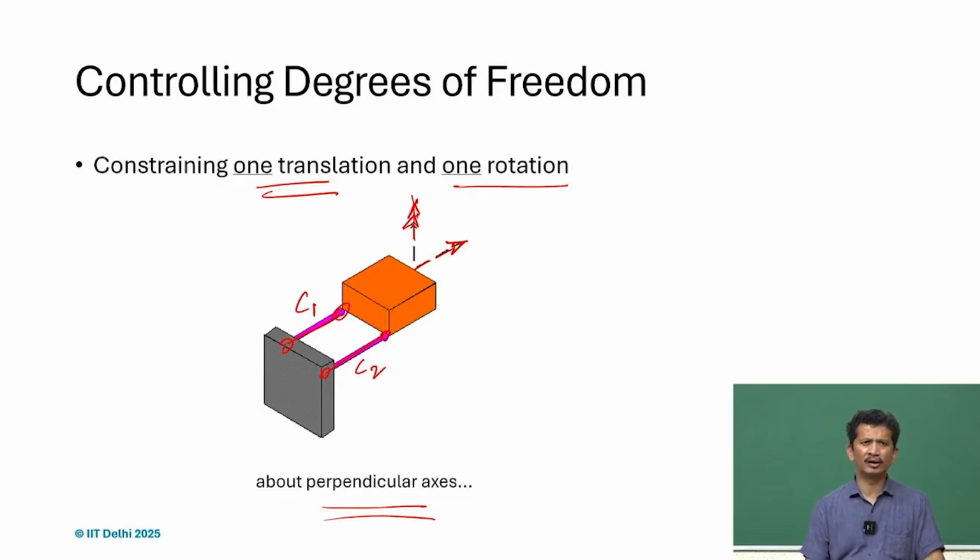So, sometimes we have to carefully check, and not necessarily use the building block for rotational constraints, although we can use it here, but it does not make sense, because just by using another linear constraint parallel to the one linear constraint here and offset and perpendicular to the rotational axis, that will provide the additional rotational constraint also.